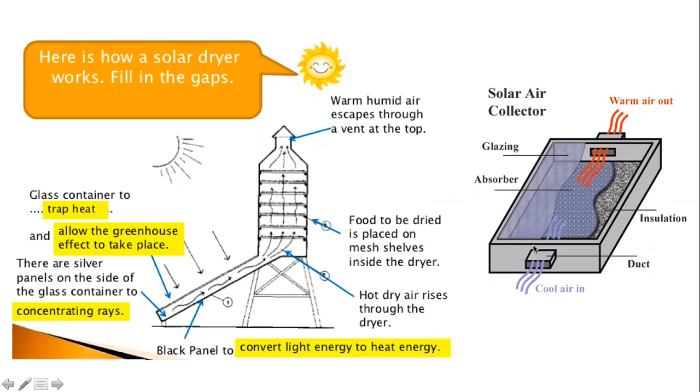And the air collector, how to design this one? Basically, we use black surfaces. For what? Black color will absorb thermal energy, and white color will not accept that, right? So if we have black color, we can trap this energy completely. And also if it is a smooth surface, then it's difficult to get that energy efficiently. Therefore we use this type of surfaces, not smooth surfaces, right?